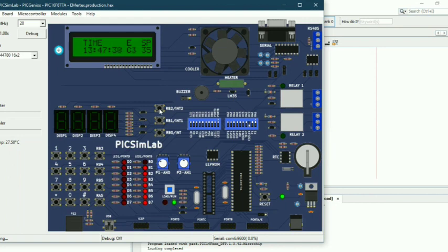If you press RB2, it reverses the gear from G4 to G3, now G2, and now currently G1. After each press, it comes backwards through the gears. We can see the display output on the LCD. It is switching across to the LED display. SP is the speed. If we increase the potentiometer, we can see how the speed varies.